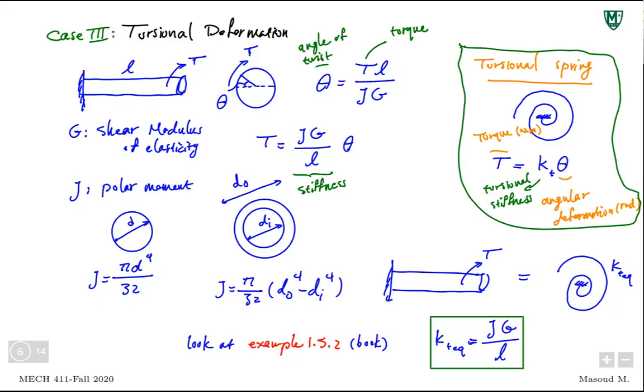Obviously, if it is severe, you're going to have fatigue, and that's going to be a big problem. But anyway, that problem gives you a simplified way of looking at an airplane's wing as a cantilever beam, and how you can use what we just said about modeling the cantilever beam, or finding the equivalent system, to look at its natural frequency and how it oscillates.